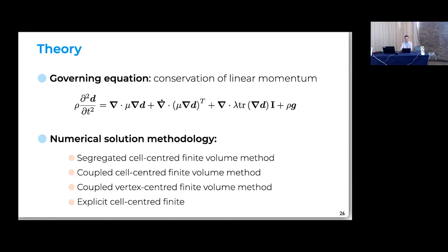This is actually pretty similar to Navier-Stokes. You'll have this term here and here in your Navier-Stokes formulations. And this would be viscosity, but here it's what's known as the shear modulus. It's like the stiffness in shearing. This right-hand side term, normally you'd have grad P, the pressure gradient. This is like a pressure term. It's just that normally in solids, you calculate the pressure directly from the displacement or velocity field. You don't have it as an independent variable.